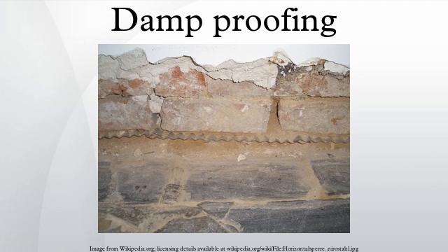Health and safety. Some DPC materials may contain asbestos fibers. This was more commonly found in the older, grey sealants as well as flexible tar boards. Other possibly hazardous materials include the use of lead sheets as a DPC material.